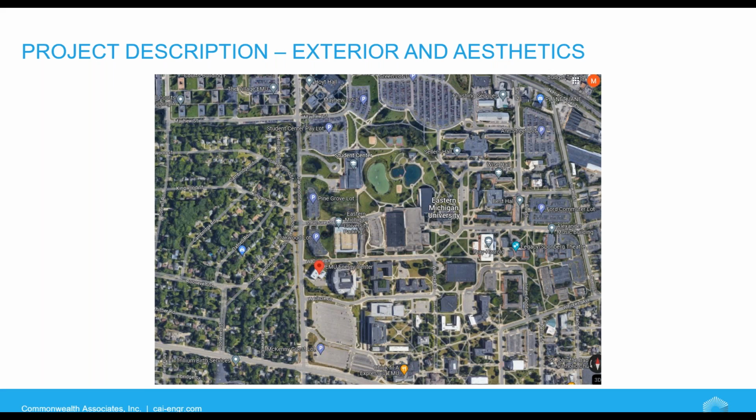The goal of the project was to maintain or improve the exterior look of the building and any equipment placed outdoors. So they did investigate placing equipment on the roof to try to hide it, but as you saw, the equipment either ended up within the building or outdoors at grade for structural reasons. The outdoor equipment was then concealed using fencing, berms, and trees, with the added benefit of the berms and trees mitigating some of the noise from the reciprocal engine and the compressors.